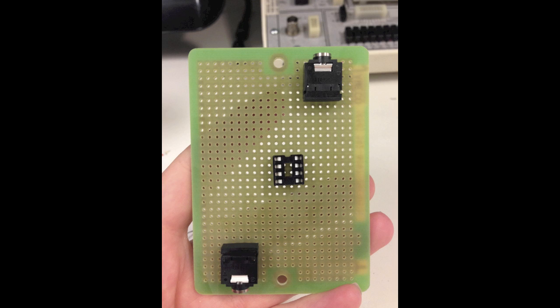You'll want to place the audio jacks as close to the edge of the board as possible. This way you can plug in the audio plug, the auxiliary cable, without having to bump into the board too much. So just try to keep those as far out to the edge of the board as possible. I chose to put mine near the screw hole locations on the board just for convenience, but you can really put them anywhere. Just make sure that you plan out your board before you start soldering so you don't have to remove things later.